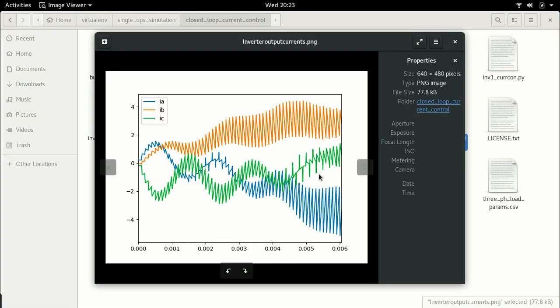So we're getting some very weird waveforms, but most important, like I said, what you have to be worried of is if everything is 0, or if everything is 10 raised to minus 9, then it's a problem. The other problem is if everything is 10 raised to 37, then it's a problem because now you have instability. So these two are the extreme cases that you have to be worried of right away. Something like this, even though it looks weird, is actually promising that it's probably working. Alright, so let's stop for a while.